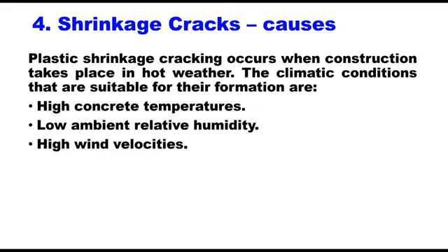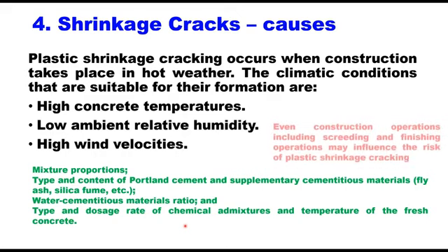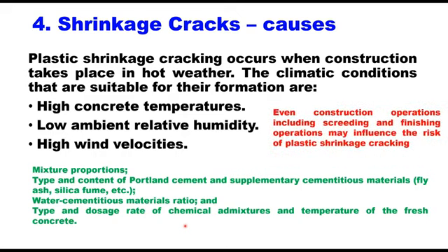The climatic conditions that are suitable for their formation are high concrete temperature, low ambient relative humidity, and high wind velocity. The concrete properties are also responsible for shrinkage cracks, like type and content of Portland cement and supplementary cementitious materials, water cementitious material ratio, and type and dosage rate of chemical admixtures and temperature of the fresh concrete. Even the construction operations, including screeding and finishing operations, may influence the risk of plastic shrinkage cracks.